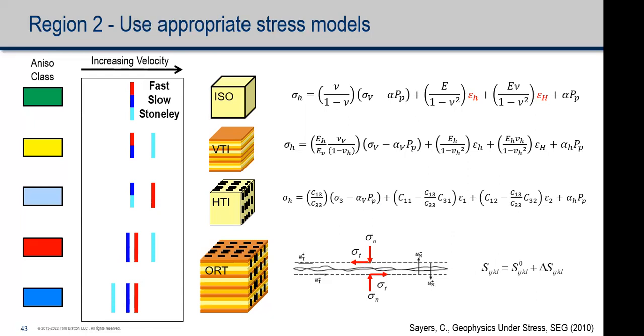One of the things that excites me is the distributed strain sensing from fiber optics. Historically, when we calibrate, we have some in situ measurement, and we adjust the strains so that our model matches our data, for instance. Having an independent measurement of strain, even if it's only vertical or only horizontal, I think is important, and is going to add a lot of understanding in the future.